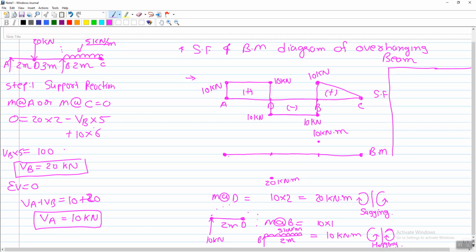So in this case, first of all, due to the point load application on the left hand side, you have to draw this diagram as a straight line, all right? So yes, it's a straight line, and then after up to point B there is no application, no load acting over there other than the point load.